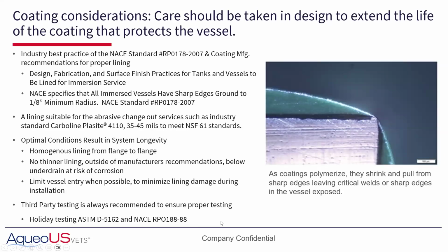There's third-party testing that can be done. It's actually called a holiday test. It's an ASTM standard D5162. So again, this is something that a third party can do, and it's highly recommended to make sure that you aren't having any potential corrosion issues.